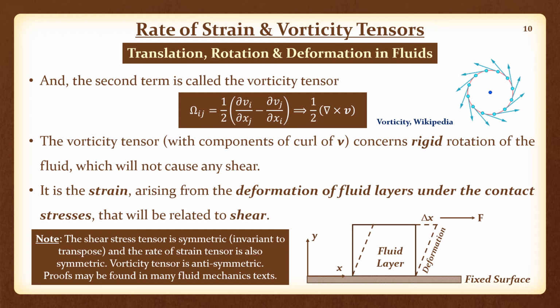And in the opposite scenario, where the fluid is flowing in the y direction, and by friction, molecular momentum transport causes the momentum to be transported in the x direction, that would be captured by tau xy. These two are equal. It doesn't matter which direction is the direction of flow and which is the tangential direction of molecular momentum transport, right?